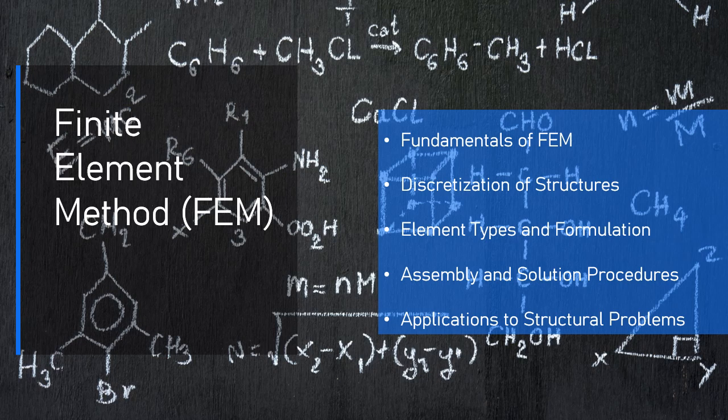4.7. Fatigue and fracture analysis. FEM can also be used to assess the fatigue life of structures subjected to repeated loading and to simulate the progression of cracks or fractures under dynamic or cyclic loading conditions. Application example: fatigue analysis of an aircraft wing, which is subjected to repeated aerodynamic loads and pressure cycles. FEM can help predict where cracks may initiate and how the structure will fail after a certain number of cycles.